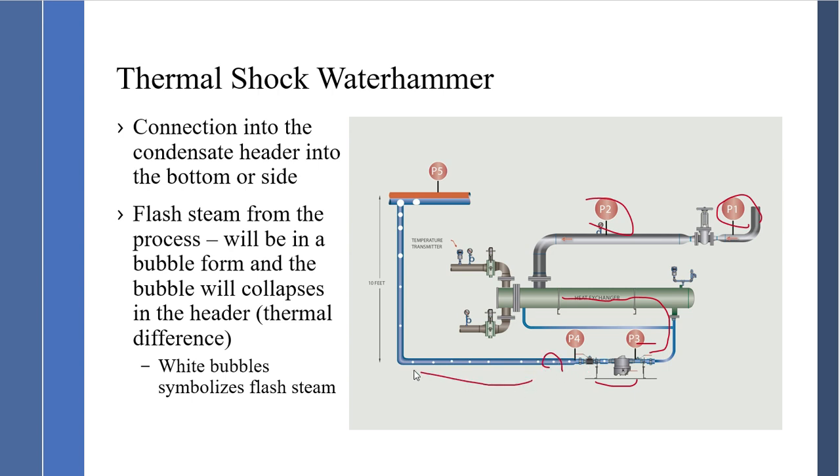As it carries along up the condensate line, pressure is reduced and the bubble will increase in size. When the bubble comes in below the condensate level in a condensate line, the bubble will collapse and you'll hear ping, ping, ping, ping. Now, if there's a higher flow of condensate, the bubble will be much larger and you'll hear bang, bang, bang.